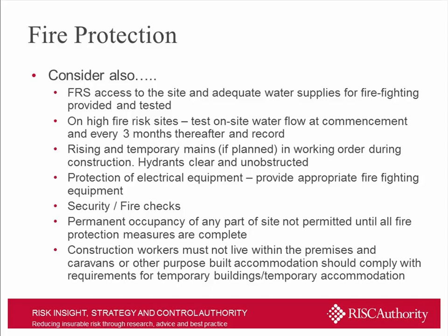And then touching on the potential for deliberate fire setting, ensuring that you have adequate security, and as part of that routine checks, particularly at the end of the day or while the site's unoccupied, to ensure that there's nothing of any significance from a fire safety perspective that needs to be addressed, or any incipient fires.